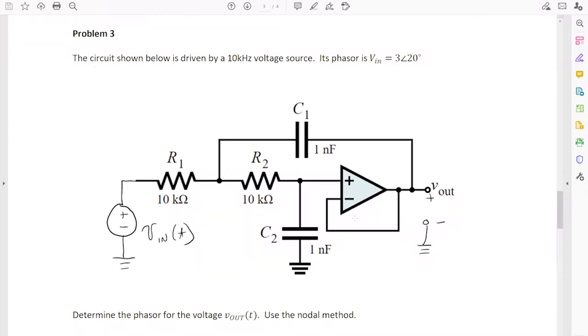So one thing about my golden rules, and maybe this is the key thing about the process, is I always have to find a way to set the plus and minus terminal to some fixed value. In any of these problems, V minus and V plus are always going to be set to some fixed value, right? So in this case,